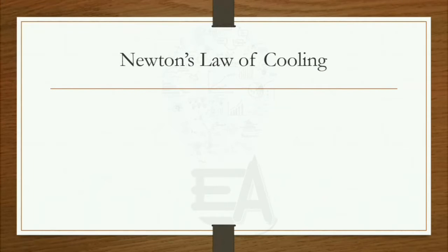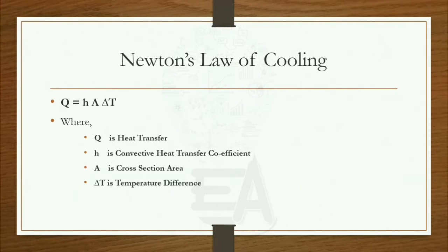Let us discuss the law which governs the convection heat transfer. That is Newton's law of cooling. So what is Newton's law of cooling? It is Q, which is the heat transfer, equal to convection heat transfer coefficient h. Its unit is watt per meter square Kelvin. The convection heat transfer coefficient is used most in heat transfer sums, so its unit is important and we have to take care of it, that it is watt per meter square Kelvin. From the formula we can see the convection heat transfer coefficient has a unit of watt, which is heat transfer, by meter square Kelvin.